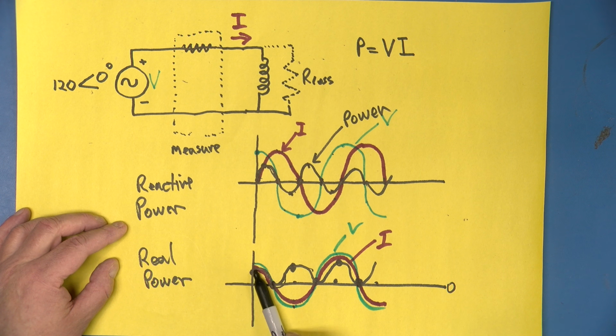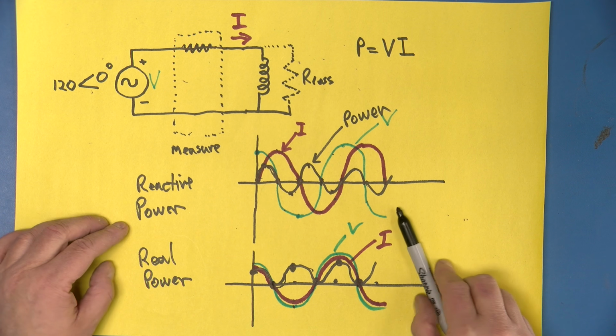And if we multiply them on a pointwise basis, what you can see is there is a pulse of power at the peak of each of the voltages on an AC cycle. So we have a burst of power going into the load, then it goes down to 0, then it goes back up to another peak, and we get these pulses as you might expect.